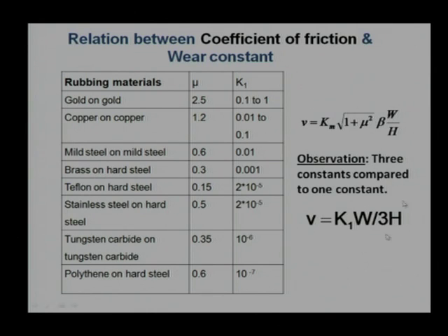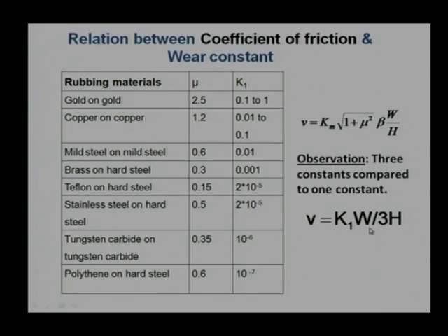In my view, using the Archard equation is still preferable compared to using the modified adhesion wear theory equation or the Rowe equation, because it has a lesser number of unknowns. And wherever there is a lesser number of unknowns, and we know that this equation cannot be relied upon as it is, we need to do some experiments to find out the results.